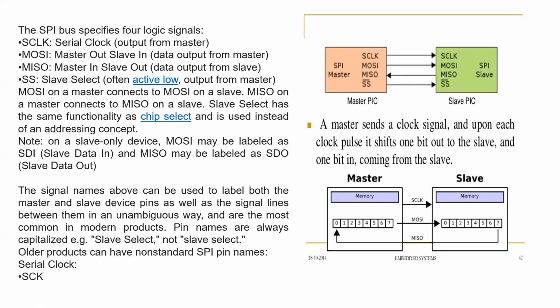As we were saying, in I square C we have 2 lines, serial data line and serial clock line. First it will send the clocks to all the slave devices. Then it will send the slave address. If any one of the slave addresses matches, it will send the acknowledgement bit to the master of the I square C. And once it gets the acknowledgement, it will send the data. In a similar way, I am calling your register number and you are responding to me. That is my I square C.